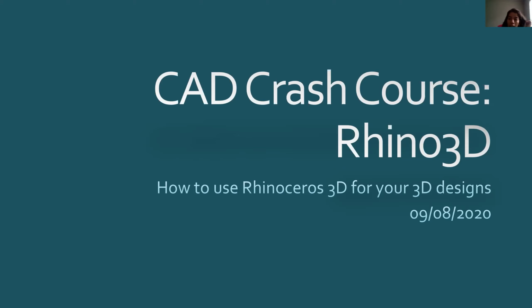Actually, I have not heard about this software earlier, Rhino3D. This is very new for me. So how is it different from other 3D CAD software? Right. It's a little bit more geared towards sculpting, perhaps. Instead of going straight from a sketch into the third dimension, this one you have the option to start with solid shapes and then manipulate them. So you can start with your poly surfaces and then play with meshes at the same time, and it's a little bit different.